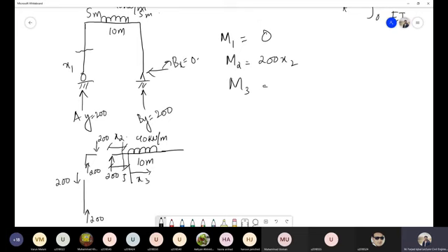Achha. Actually, there are two ways to take this. I showed, for example, you could have taken this x3 from this right hand directly to this point, to any random point from the center. But I intentionally showed you this x3 from this center because in some of the problems you will find that they would take the reference at this point. In x4, we would take this distance x4 just so that you should be aware. Even if you take x3 from this particular point, or you take this as reference, you need to consider all the forces that are acting to the left of this point.